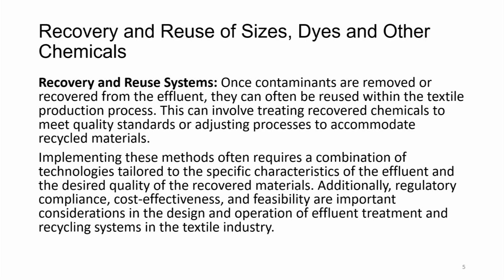I will give you an example. Suppose in a dye bath, a lot of dye is still remaining. It need not even be recovered from there. The only thing is, by a color spectroscopic method, one can adjust the desired color by dosing a lesser amount of dye in the second dye bath and using it, so that the net result gives the same as the previous result of dyeing.